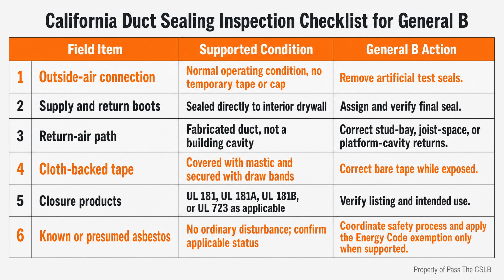Before drywall, I use a short supervision check. Is the duct system complete enough for the chosen test condition? Is the air handler included or not included? Is the correct 4% or 5% limit understood? Is the rater scheduled? Are the joints exposed so failures can be corrected?